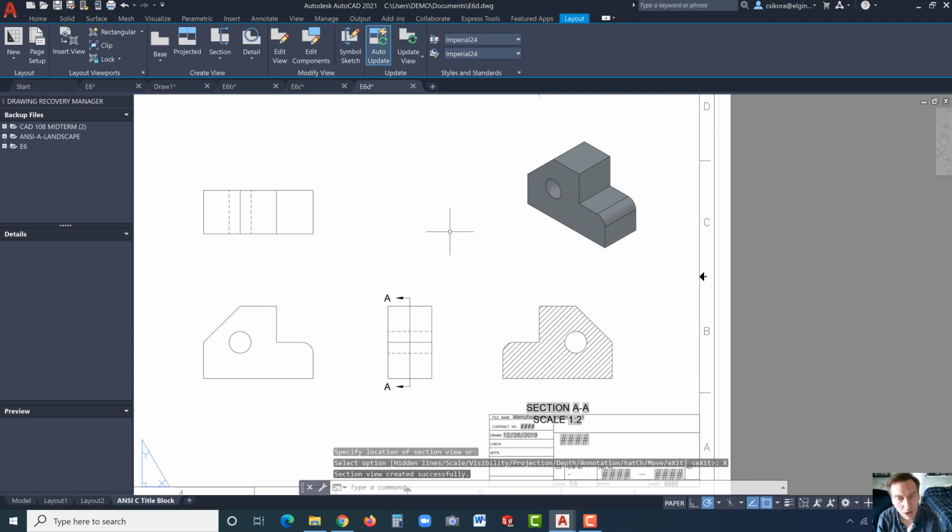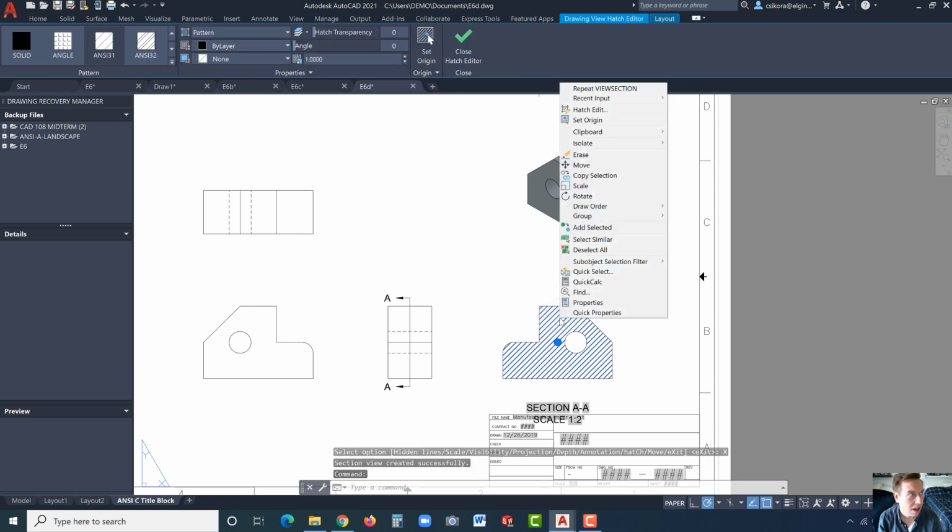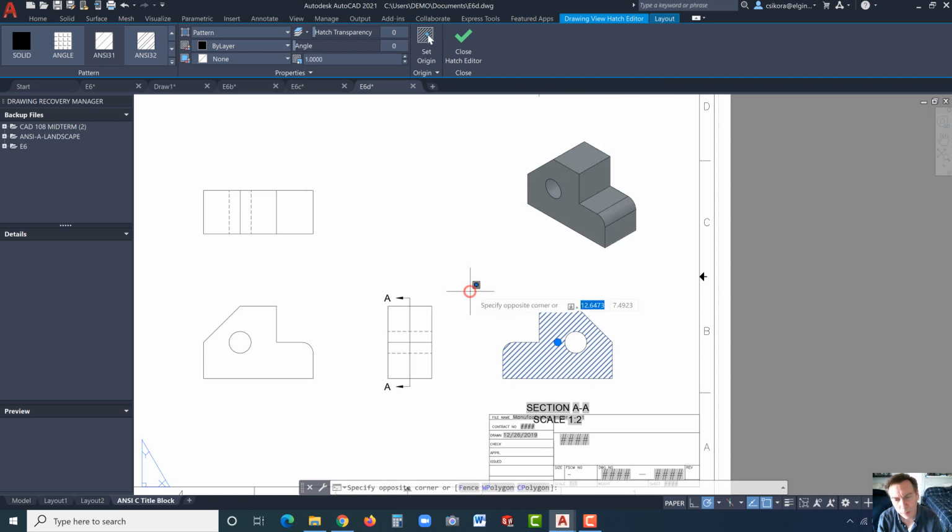And it should automatically crosshatch. Now if you don't like the crosshatch, remember, you can always click and then right up there we get the crosshatch information. I was going to go to the properties, but this is fine too. And here you could adjust the angle. You would be able to put in, if you wanted to rotate it 80 degrees, 90 degrees or whatever. And in this case, it actually came out quite nice, so I'm not worried. And I'm going to hit escape.